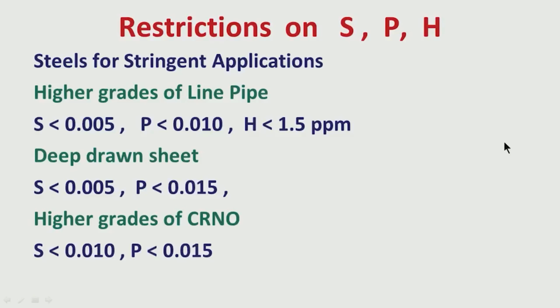So, for hydrogen analysis, what is important is you put the sample under liquid nitrogen and then take it to the hydrogen analyzer. That will give us a more realistic analysis. We should get a realistic analysis only when the sample with hydrogen is kept in liquid nitrogen before it is put into the hydrogen analyzer.